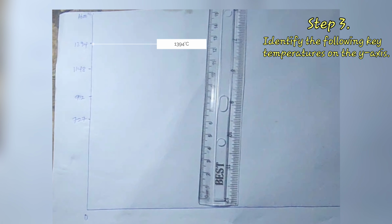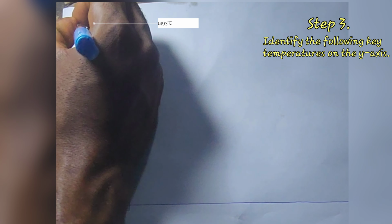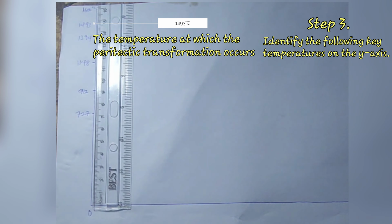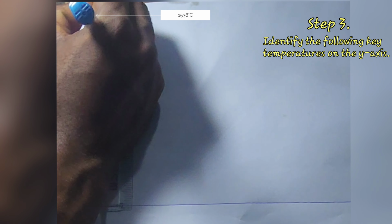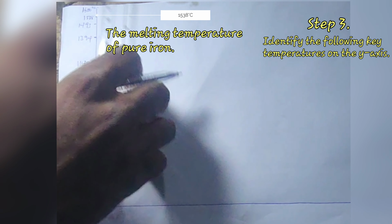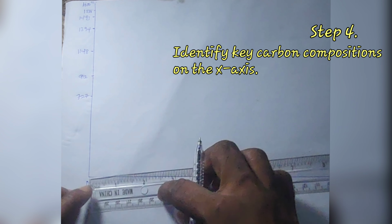1394 degrees Celsius. The formation of delta ferrite at high temperature. 1493 degrees Celsius. The temperature at which the peritectic transformation occurs. 1538 degrees Celsius. The melting temperature of pure iron. Step 4. Identify key carbon compositions on the X-axis.